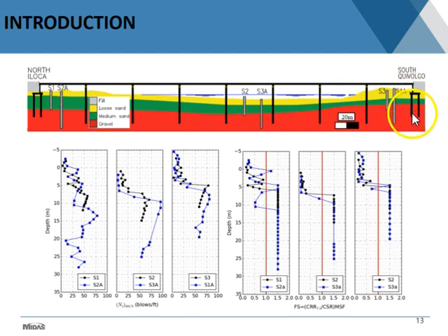And the main reason was really, well, from what I was told, not because of liquefaction, but they were worried about scour due to the river flow. I mean, this is a river that from time to time has a lot of flow, and the erosion of the material was really the concern here. So they made the piles rather long to avoid having issues in that regard. But in this case, they also serve well for the purpose of lateral spreading and the control of the deformation.